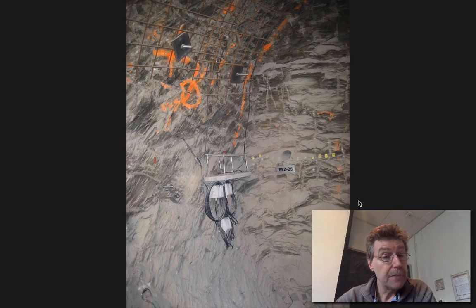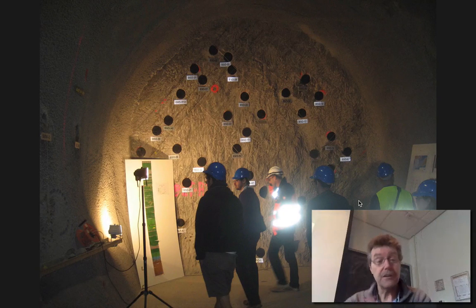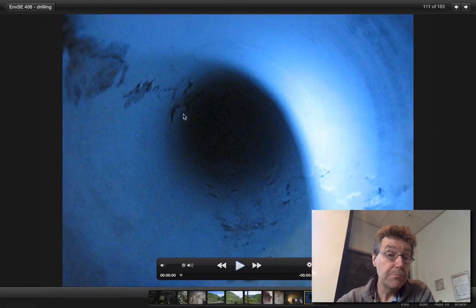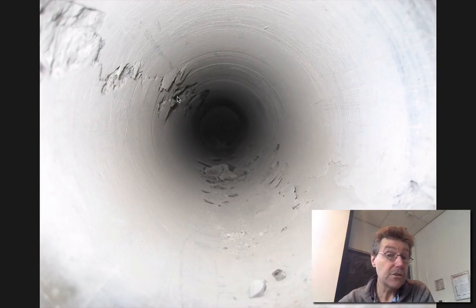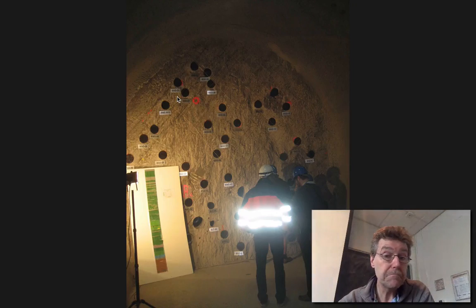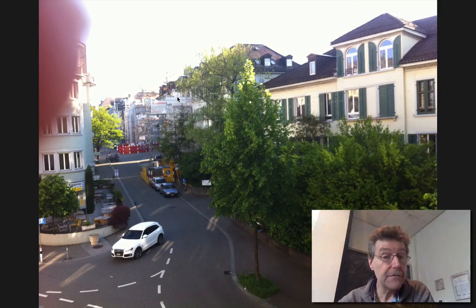It's an old mine, I'm not sure for what, but here it's used to look at measuring permeabilities, seeing how permeabilities change with stresses, doing tracer tests to see how fast flow occurs, and looking at borehole breakouts to see what the stability of wells might be that you put radioactive canisters into, to see if they'll fail. To do fault reactivation experiments,